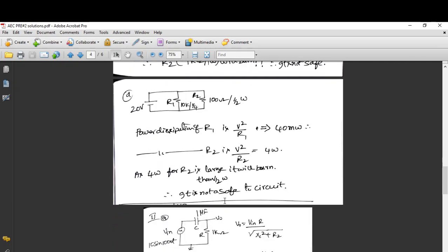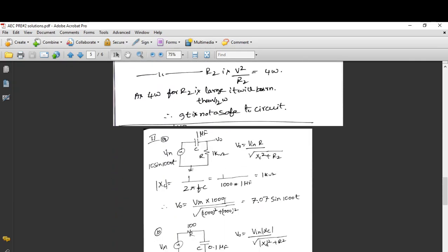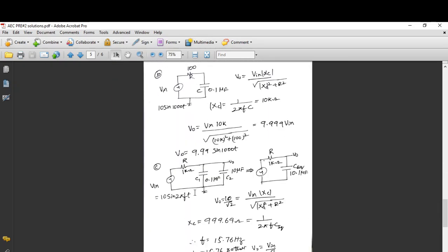As you look into the solution, as we saw in the first video of the second solution or second task, it goes like this. This is your given circuit, so that can be simplified and rewritten by considering these two capacitances as parallel capacitance. Then the equivalent capacitance is this, and output voltage V0 is given by, of course I am writing just the magnitude of it, V0 by root 2.